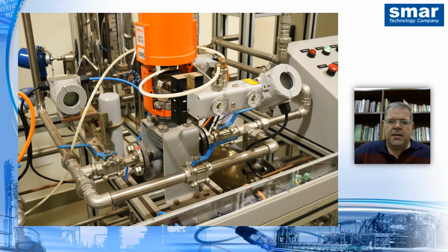We also possess, besides the automatic controller, a bypass where we can manually operate the plant, allowing us to close this valve and that valve. We eliminated the main proportional valve, and thus, through the bypass, we managed to introduce water into the circuit for our flow meter and our tank.